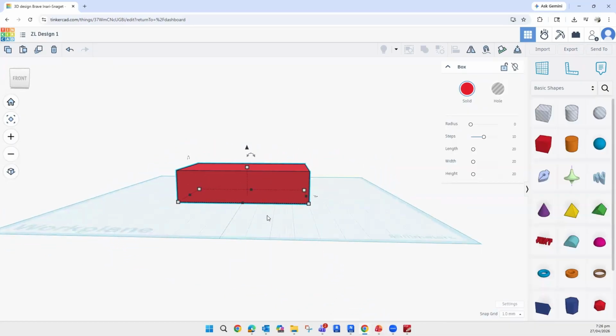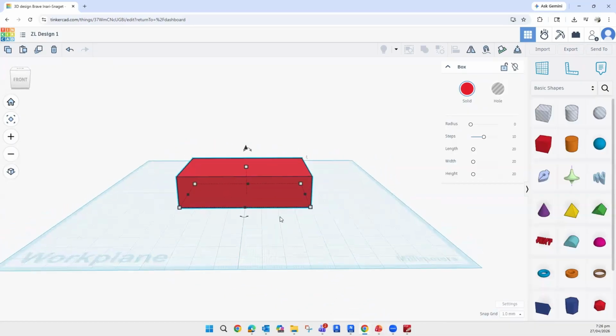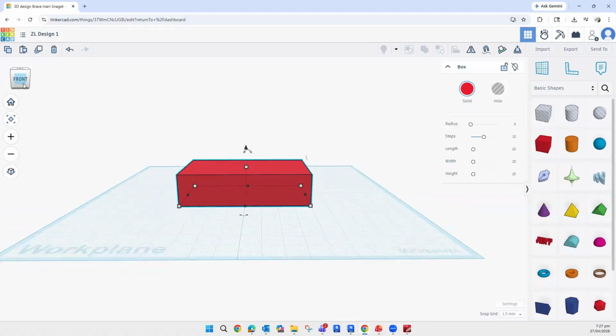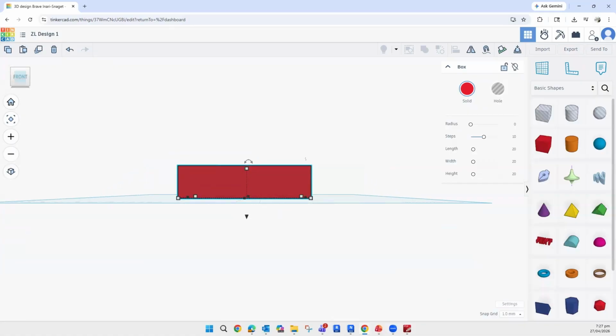After that, height. Height is also the same. For height, we don't know what the shape looks like. We're going to click this front view. So that will go to the object elevation. So we go to the front view. Yeah, you can click this top point, the top. You don't click the bottom one. The bottom is the width and depth. So that is the height. We make it maybe 30.